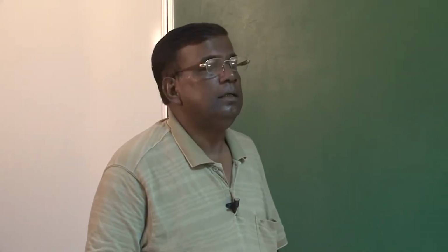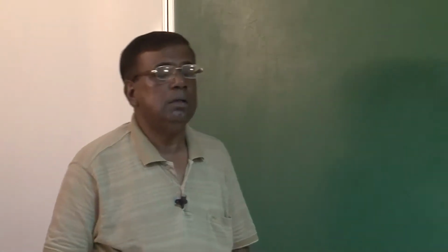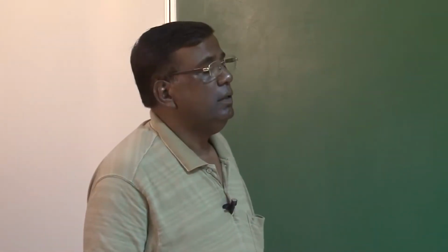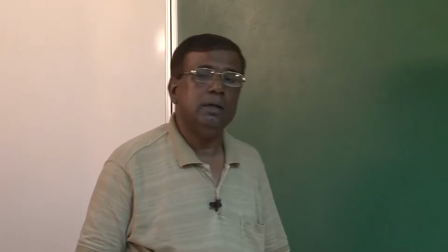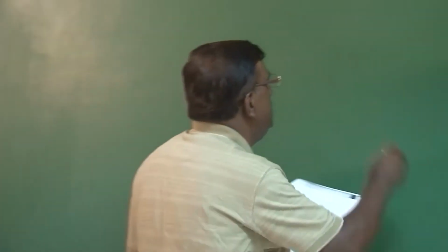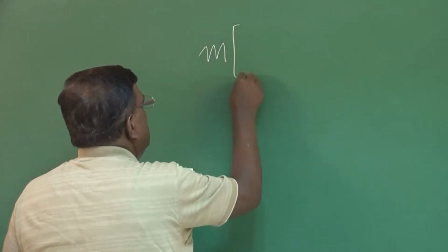We all know that if I am using Newton's laws of motion, then I have to work in reference to an inertial frame of reference. We have found a way to equivalently work in the body frame by applying appropriate additional corrections or terms, so that we still can work in the body frame, but we don't violate the condition that Newton's law of motion is valid in reference to the inertial frame of reference. And doing that, we found the equations. Just I will write one or two of them.